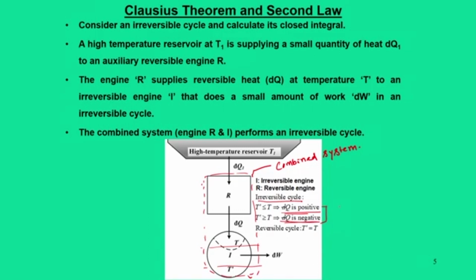We are now going from an initial state I, during an irreversible process, to the final state F, and back to the initial state, to analyze this relation in an irreversible process, on this temperature-entropy diagram. We start at state I first, and we want to go to the final state F. Our analysis is focused on an irreversible process, which is proceeding in this direction. Now, by a return reversible path, we are trying to say something about the entropy for this reversible path.